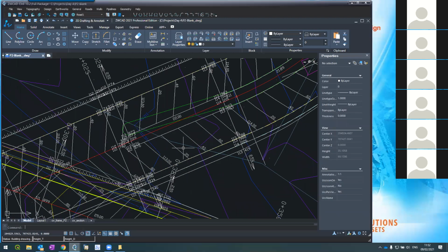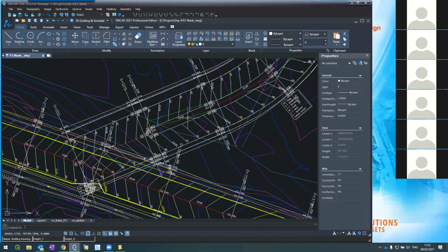So the only thing that I will need to do is to create another segment from here to here with the median to the left. And that's it. But these are classic problems that we see. Many times people send us projects to review, saying, oh, I didn't get what I want, but this is the classic problem. The typicals in the extract are not suited to the geometry. So the system doesn't know what to do.